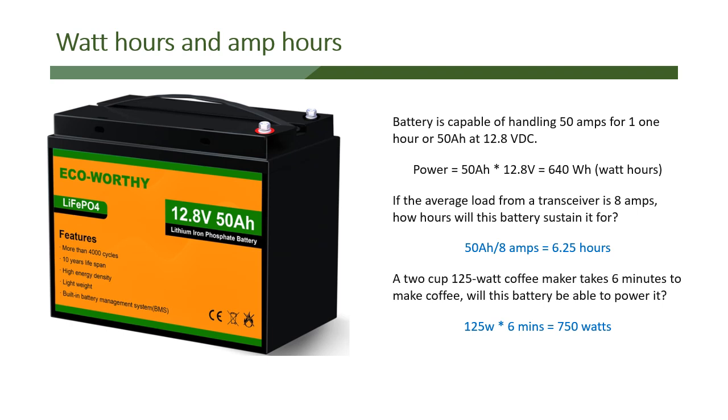So understanding these kinds of calculations of amp hours and watt hours and what you're drawing tells you how long that battery will be able to power the devices it's intended to work for. And so if you're working in the field like I often do, transmitting out of parks or at campsites, then I carry enough batteries sufficient for me to operate for the period of time I'm away at the power levels I wish to be at. So on average, I don't use more than 20 watts when I'm transmitting. So therefore, I can have a battery load that will last me for 12 to 24 hours, depending on which radio I'm using, which battery I'm using.